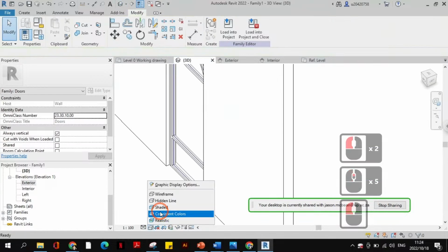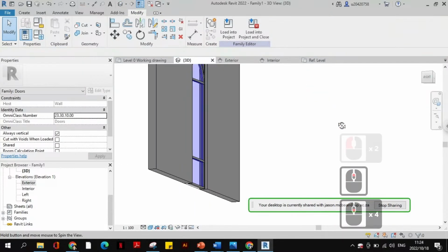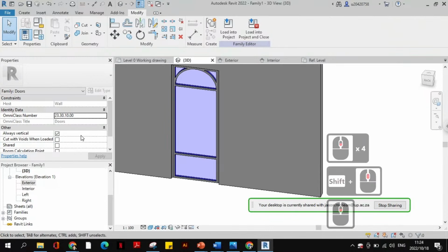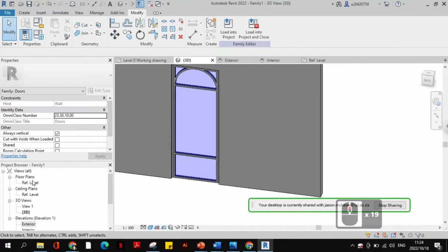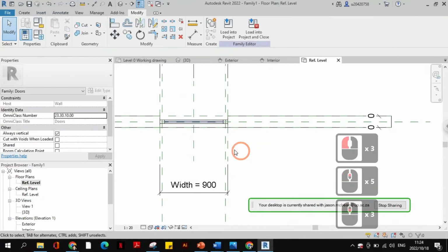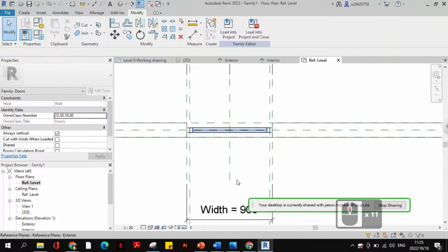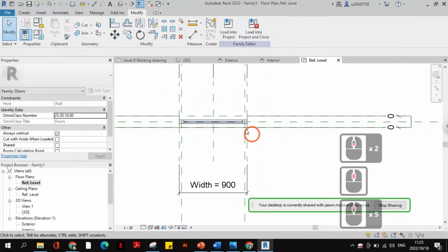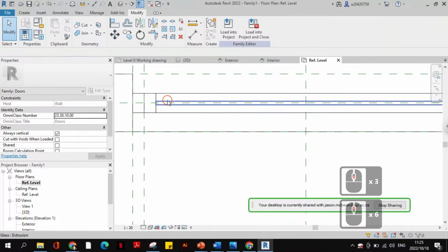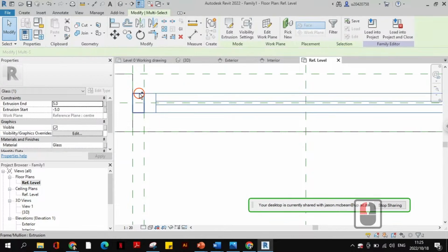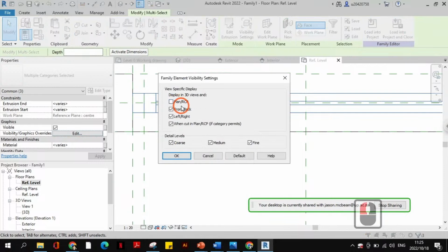Now this is where things get just one last little hurdle. Now you need to decide what side the door swings out. Now this is all 2D information. So now we select all the 3D stuff. So select that, and select that. Now, if you go to visibility and graphics, when you go to plan view, you never show this in plan view, and you never show this when cut in plan.